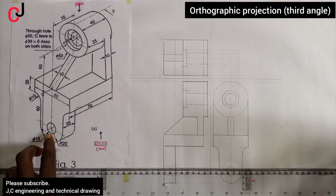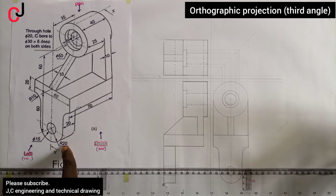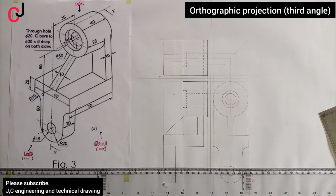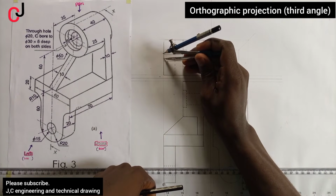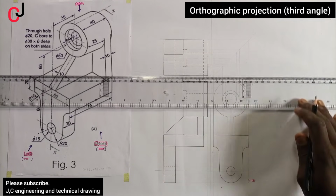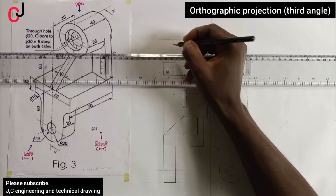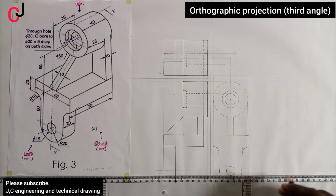Then the next thing is that there's a circle here of 15 diameter, so you measure 7.5 as radius, place it at the center line, indicate it with a point, also with a point, and then you indicate that point with what? A broken line, indicating that there is a hole. This is a circle, it's a hole passing through,